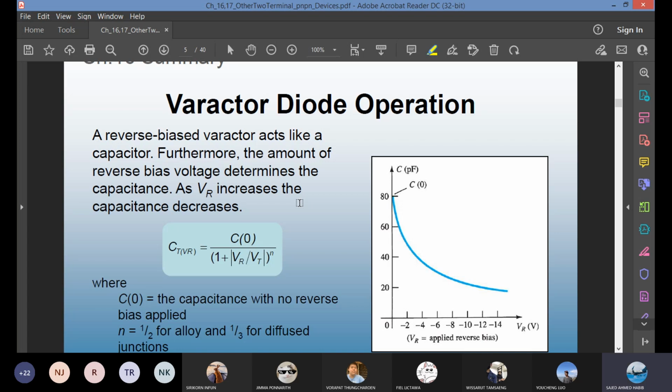Think of the construction of a capacitor. How do you create a capacitor? Fundamentally, you have two parallel plates, right? One has plus polarity, the other one has minus polarity. Now think about the depletion region. Two ends, the left side and the right side. In the middle, there's a wide space. Also in the depletion region, there are carriers which do not take part in conduction.